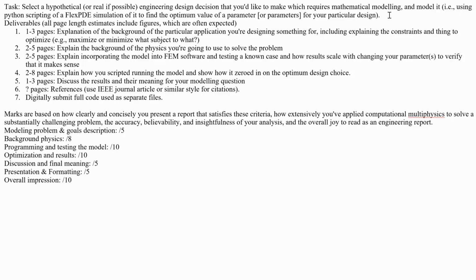So examples of this would be, imagine you want to build a thermal strap, let's say, to cool down a computer on a satellite, and you only have conduction to do it. Then you want to design the optimum, let's say, width of this thermal strap so that it weighs as little as possible, but keeps the temperature below a certain limiting temperature, let's say 60 degrees C, after 12 minutes of operation.